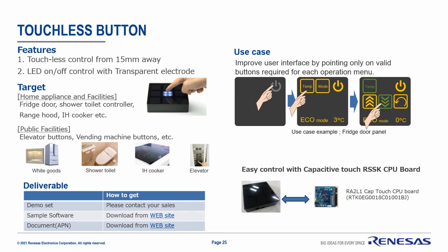Touchless button. As explained, we have also developed a reference design concerning the touchless button technology based on self-capacitance. We are able to detect the presence of a finger at 1.5 cm without cross effect. The overlay is transparent and could be easily adapted for any kind of applications.